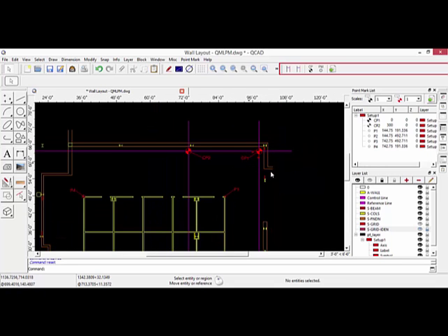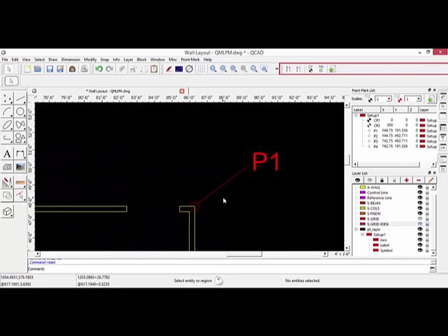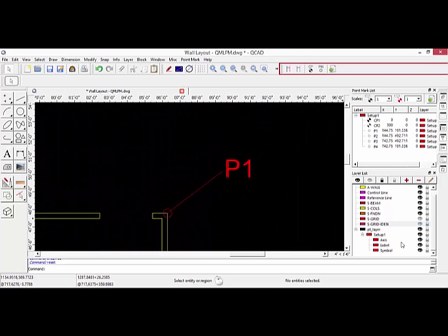Now, just like we have labels for the control line and the reference line, if you scroll down under the point layer, you'll see that there is the axis itself, the label, and the symbol. So if I zoom in real close here, you will see that there's additional information. If I turn off the label, you can then just see the points in there. You'll have the axis. The axis is actually turned off.